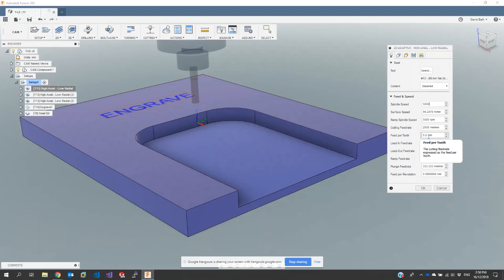Now, one thing that you need to think about is, even if the machine is rigid enough, if the spindle doesn't have enough torque to actually drive the tool through that cut, when you start to take that cut, the spindle is going to slow down. If the spindle's slowing down, the chip load is just going to get bigger, because it's now moving forward through the material, relatively speaking, faster than the spindle was previously turning. And so the problem is just going to get worse and worse. So you definitely don't want to be stalling the spindle, otherwise you're going to be generating more of a problem. So that can be another factor.